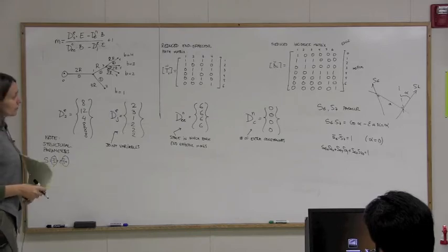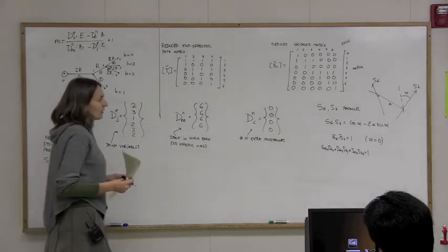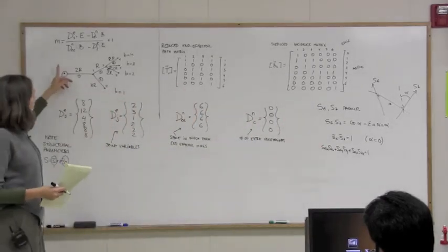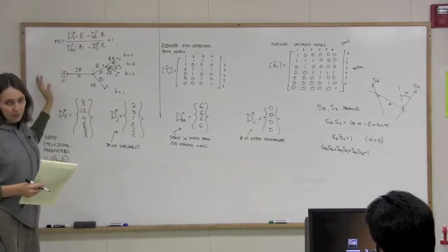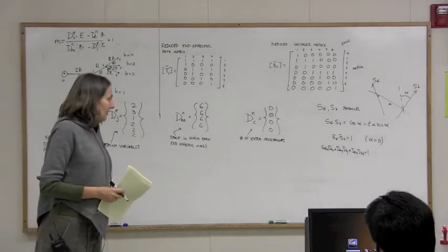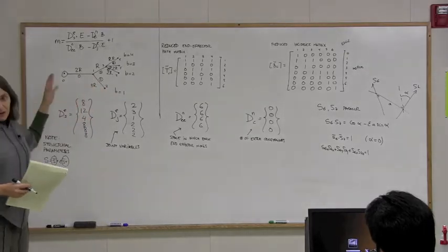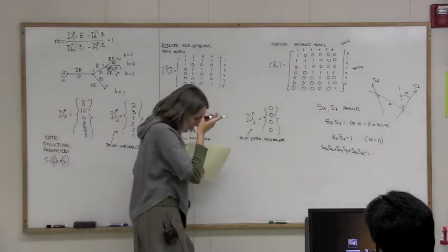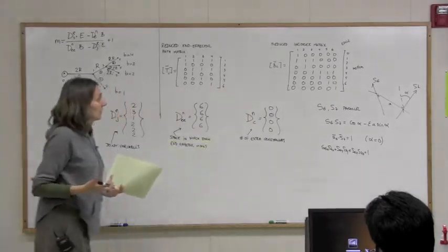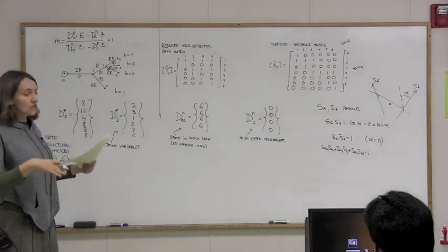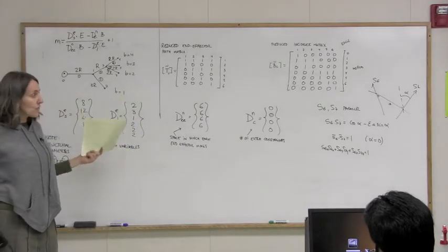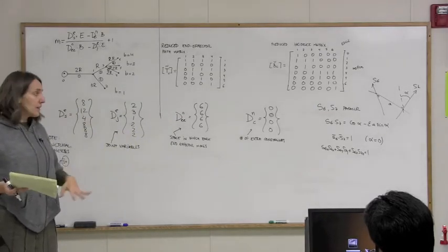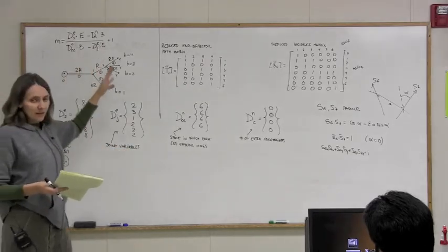And of course, if you have these constraints, and especially if you give actual numbers to some of them instead of adding equations, so for instance, you say, okay, I want this joint to be along the z direction, then you simplify your system, and you have fewer equations. You have a more limited set of solutions too. But in general, in the phase that we are in right now, which is the beginning of something new, we want to see what happens in the most general case. How many possible solutions can you get if you don't have any extra constraint? Once you understand this very well, then you can start adding constraints and making something that may be more useful.